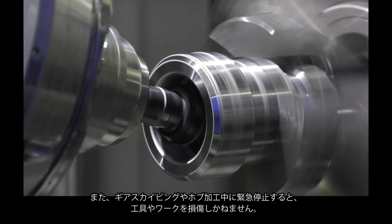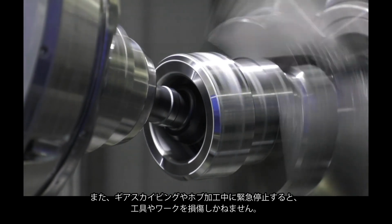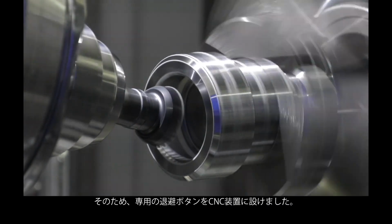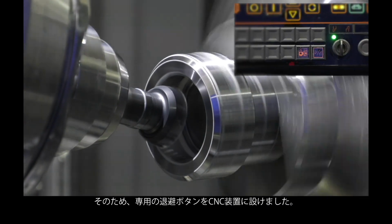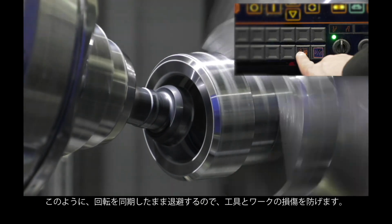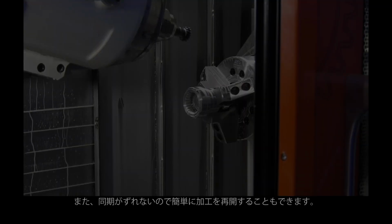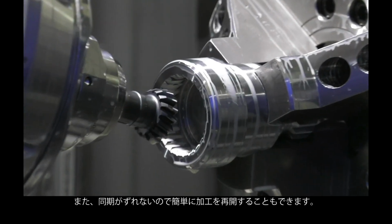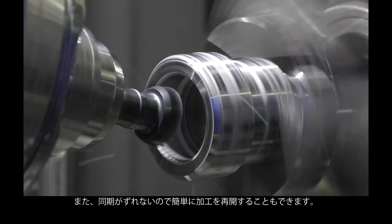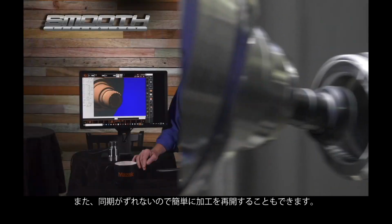When using a hob or a skiving tool, feed, hold, and reset should be avoided. Instead, we provide an escape button on the face of the control. Pressing this button escapes the cut in a synchronized manner, avoiding damage to the part or tool. After using this escape sequence, you can simply restart the cut. The timing of the gear is not lost.